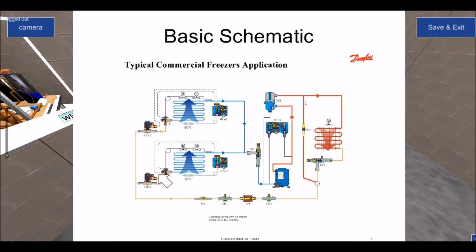And we can actually see where the control cable, so in other words, the solenoid valve gets its signal, or its 220 volt supply, to energize the solenoid valve from the room stat. So this is representing your room stat here, and effectively what happens is that when the switch is made on the room stat, we're getting a live feed to your solenoid. So you get your electrical live feed to your solenoid coil. That energizes the coil, which is basically a magnetic field, which will pull the valve stem out of the body of the solenoid valve, which means then that refrigerant can continue to flow on through the metering device and into the evaporator, and then that refrigerant is drawn by the compressor back and discharged and continues the cycle.